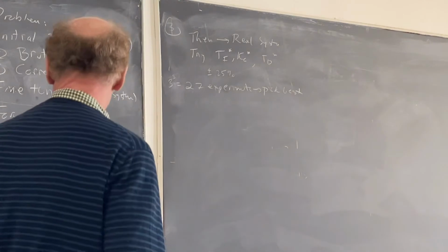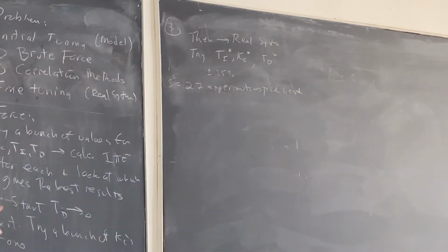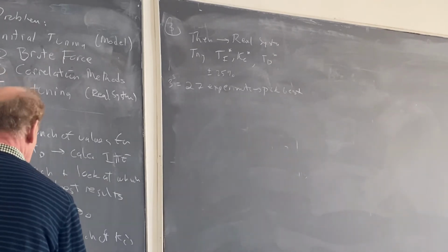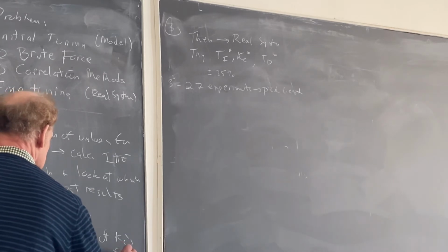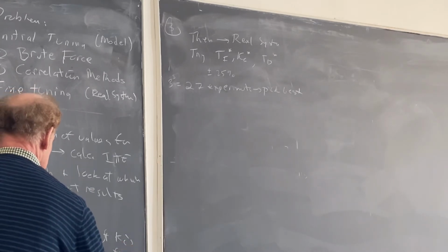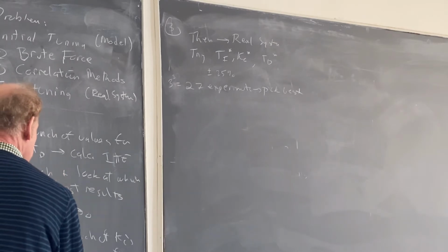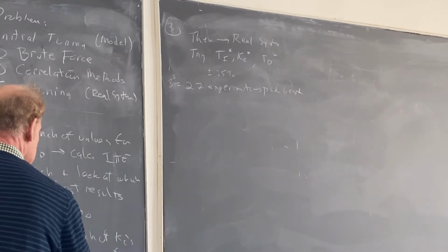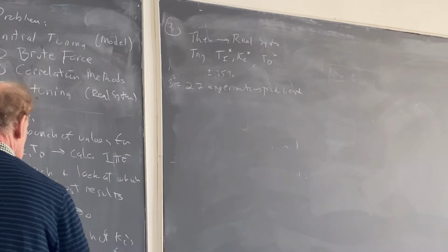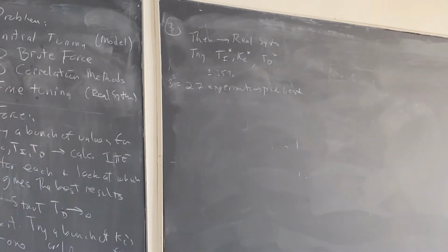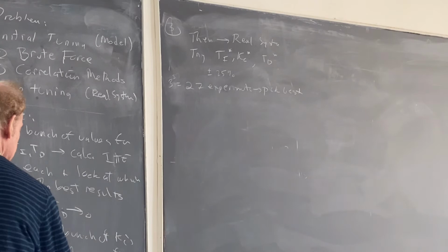Now, by the way, just before I do that, how do I do this? I should have done a couple of plots here. When I say pick TI, fix it, and try a bunch of KCs, for each KC, I would look at CV prime as a function of t. Let's say it's that, for that value. And then from this, I would get an IAE.